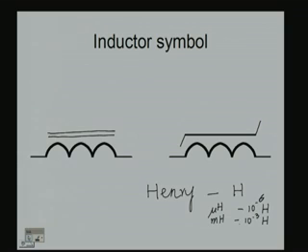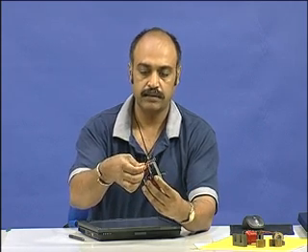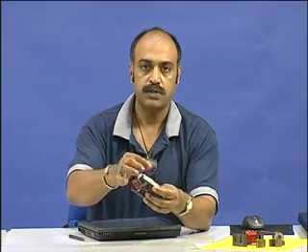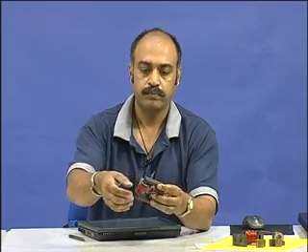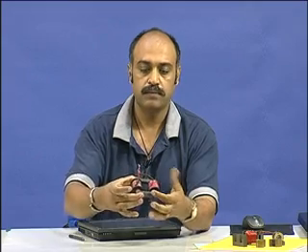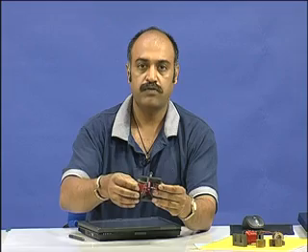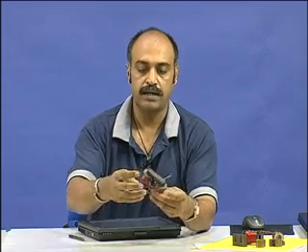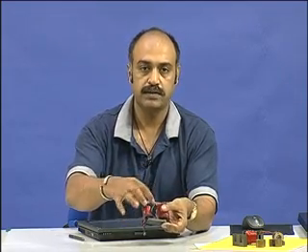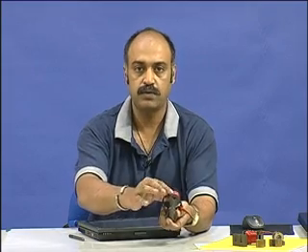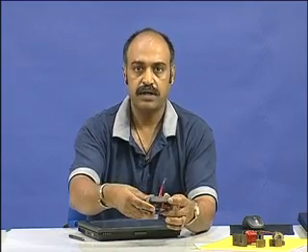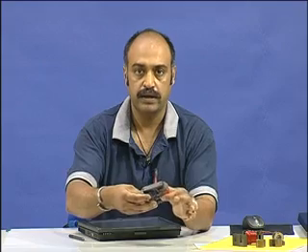Now, let us see some practical real world inductors. You see here, this is a practical real world inductor. You have these two terminals coming out here, and there is a core here and the two coils here. Of course, here for handling the current rating, these two coils are paralleled. You see that these two wires are paralleled here, taken out here, the other two ends paralleled and taken out here, but it can also be as well just one coil here.